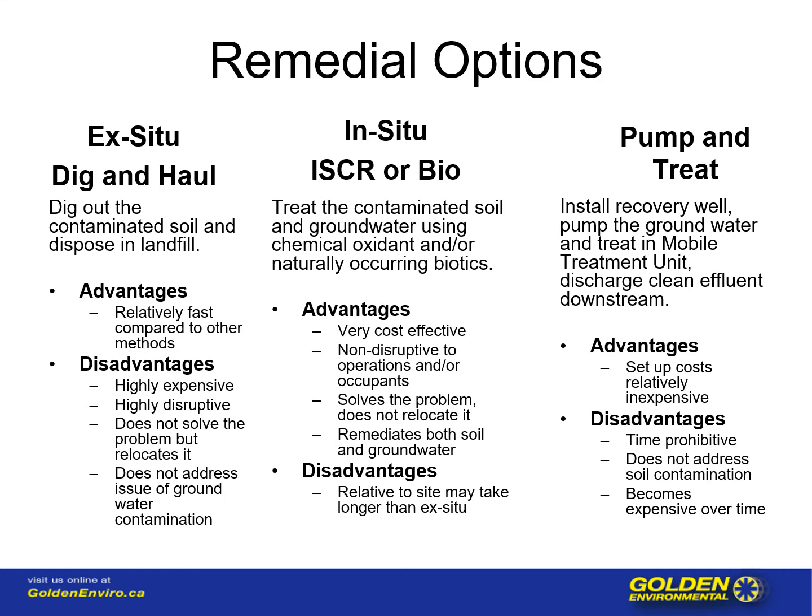If one does not desorb the contaminant from the soil, we get what's called rebound. That after one has remediated a site or done an injection with a chemical oxidant or a bioamendment, one can test the site and see that it is clean. However, over time, that contamination can desorb from the soil back into the aqueous phase, recontaminating the site.